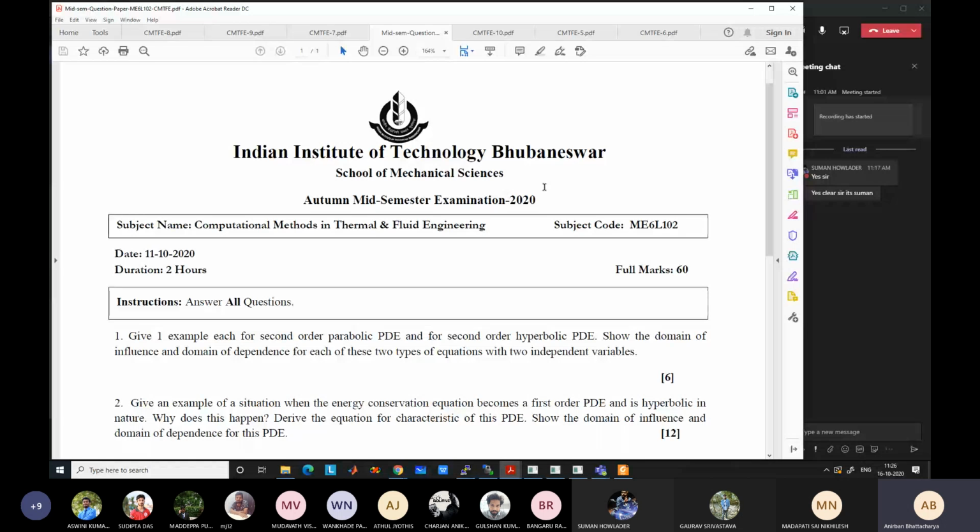Now depending on how many grid points you have, you will get that number of equations and unknowns, and you can solve those equations to get the solution. If it's an unsteady problem, you will also get a marching type of solution. So any of the problems you should be able to solve with finite difference approximation. It's not difficult.